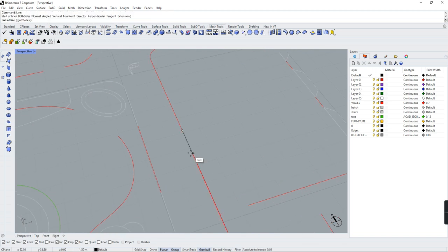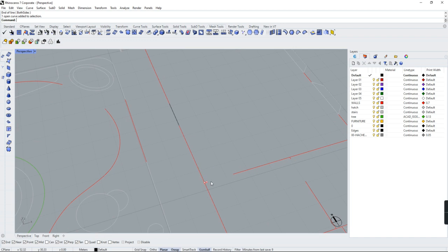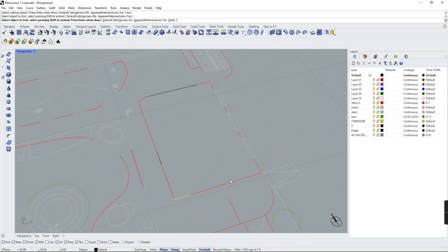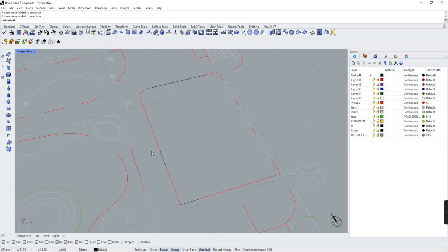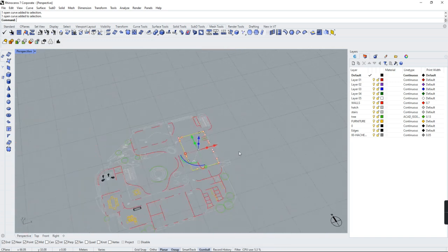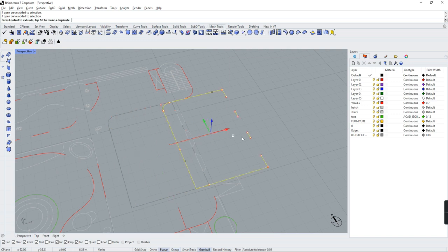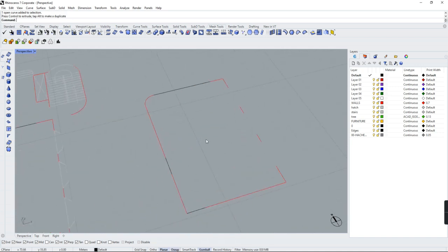Some lines I'm going to join, some lines I might delete. I'm basically making a shoebox so that I'm able to extract this. I'm going to select all of these holding shift, and I am not using the windows right now, as in these window openings, but I'll hold Alt over my movement button in my gumball, and then I'll move it on the side.